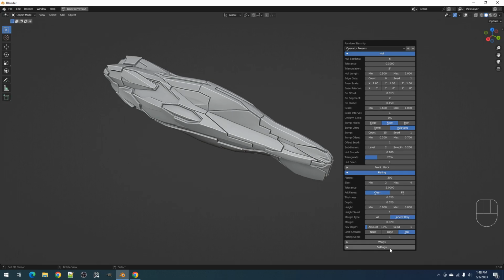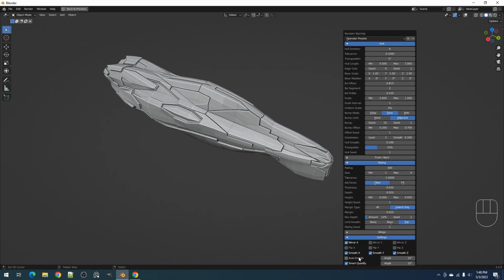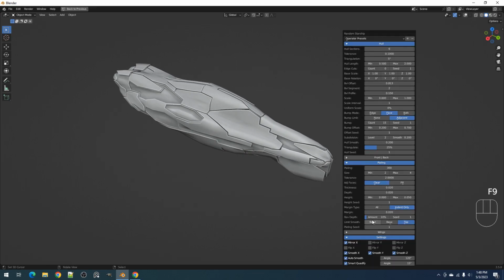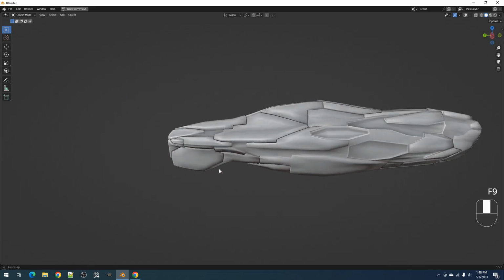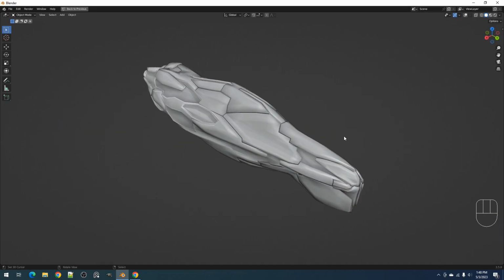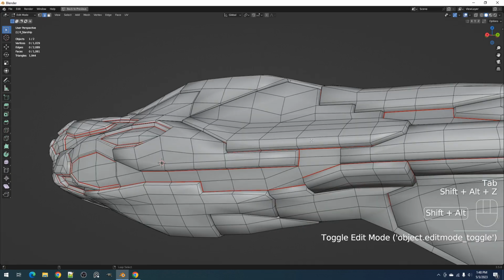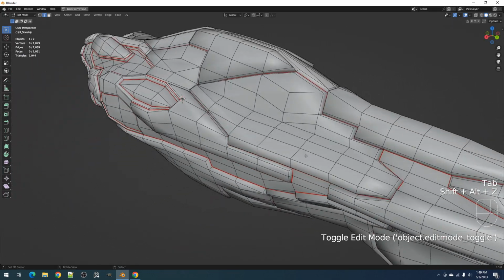The limit smooth property works in combination with the auto smooth properties in the settings category. These mark sharp the border edges on the top or bottom part of the plate insets, making it look different when using auto smooth. Using none will of course not mark anything. Using base will mark sharp the border edges at the bottom of the plate insets, making these areas sharp with the top part being auto smooth.